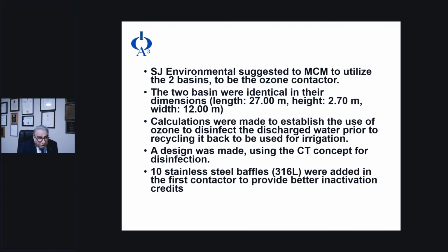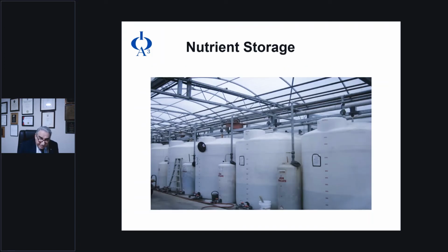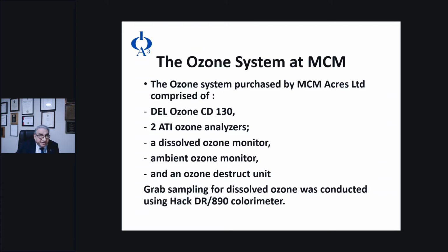Also, I suggested including baffles to improve the inactivation because of the inactivation factor credits. If you have baffles, it will be way better and use less ozone to achieve your goal for disinfection. They agreed on that, and they were installed. These are 316L stainless steel baffles. What you see here is the nutrient storage. So it's a good size application here.